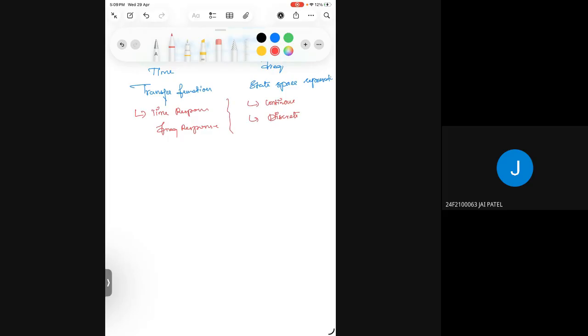These both are not completely equivalent. These are different kinds of representation in different domains. You know the common state space format, right? X dot equal to AX plus BU, Y equal to CX, where this X dot represents the change in state, or rate of change of state, like how the state is being propagated over a time period, where this X is the actual state representation